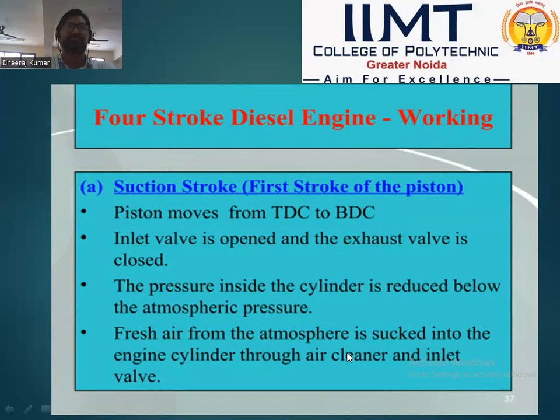Four-stroke diesel engine working. The first stroke is called the suction stroke. During the suction stroke, the piston moves from TDC to BDC. The inlet valve is open and the exhaust valve is closed. The pressure inside the cylinder is reduced below atmospheric pressure. Fresh air from the atmosphere is sucked into the engine cylinder through the air cleaner and inlet valve.